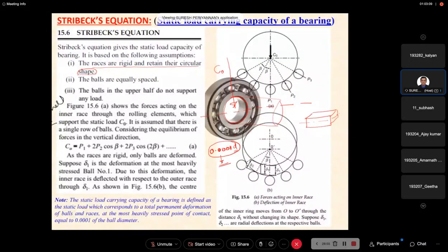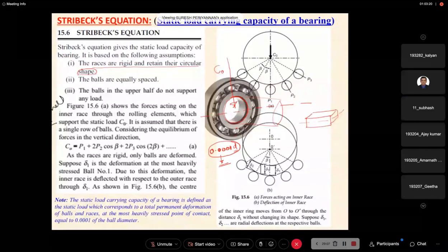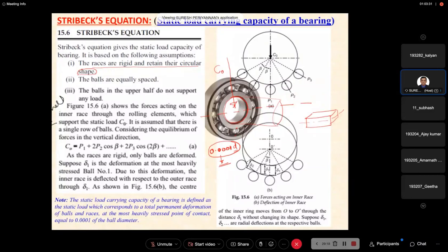This is a neutral layer, right? In the neutral layer, is any stress going to be present? The neutral layer has zero stress, right? Hence, whenever the load is acting, the beam should be plane before loading. The beam should be plane after loading. Am I right or wrong?